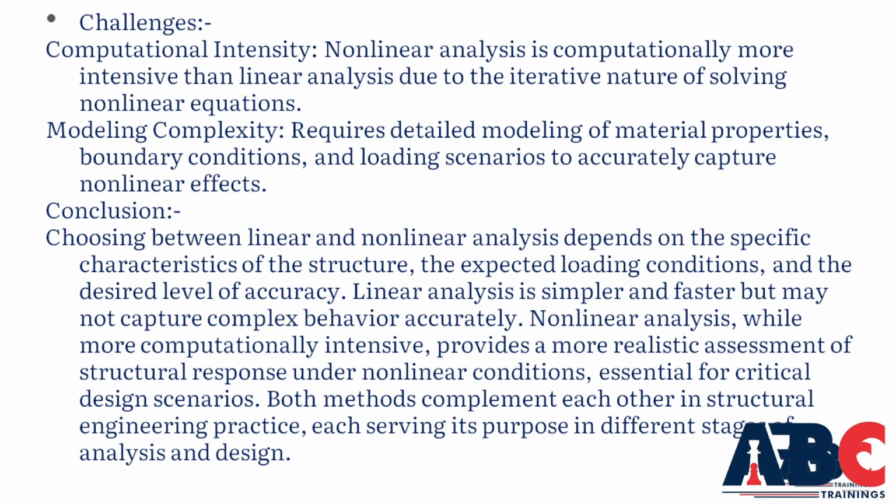Choosing between linear and nonlinear analysis depends on the specific characteristics of the structure and the location, the expected loading condition, and the desired level of accuracy. Linear analysis is simpler and faster, but may not capture complex behavior accurately as compared to non-linear analysis. Non-linear analysis, while more computationally intensive, provides a more realistic assessment of structural response under non-linear conditions, essential for critical design scenarios. For example, having a fifth zone in earthquake.